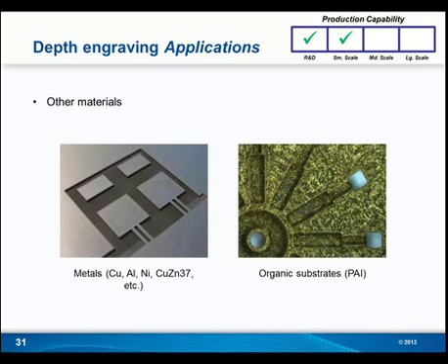And then with circuit board applications, you can do exactly what Mirella mentioned with her contact that does the multilayer. Very popular for research and development, and then for small scale production, it's becoming even more popular for microfluidic applications and microrobotics, where maybe the high scale, the laser that you mentioned before, the price points, these lower cost UV laser sources are allowing these types of applications to be done where it's an organic substrate, but the repetitions and control let you go to set depths in those materials.